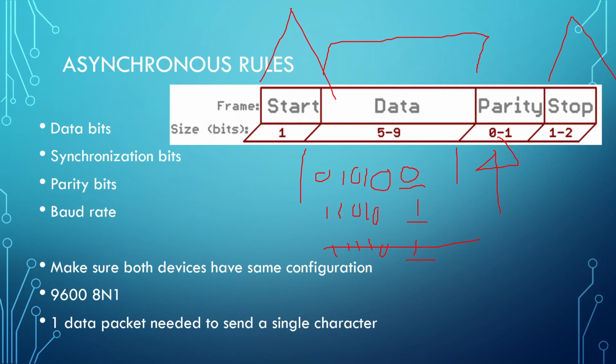So the biggest important thing when it comes to serial communication, in my opinion, is making sure everything is set up the same. Device A's settings are the same as device B's settings. As long as that's the case, you should have pretty small or non-existent errors in getting those devices to communicate. A mixed-up baud rate is probably the one that's going to happen the most. You're going to plug a new device in, and it's supposed to be this baud rate, and it's not. Or you had your old baud rate set high, and you plugged in the device like, oh, that's the default, 9600, perfect, and it didn't work. And when you do that, you get all sorts of weird data.